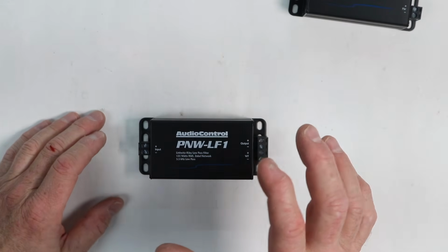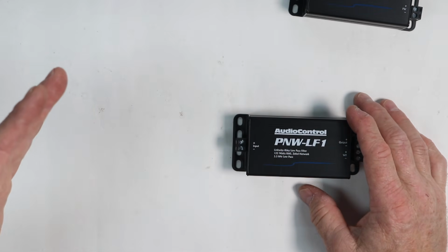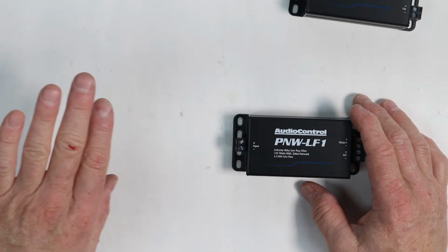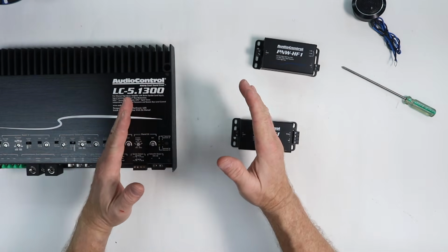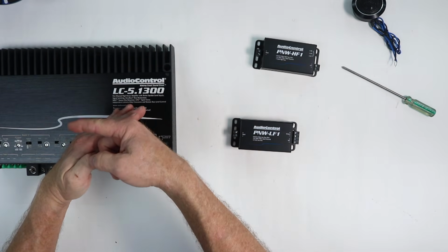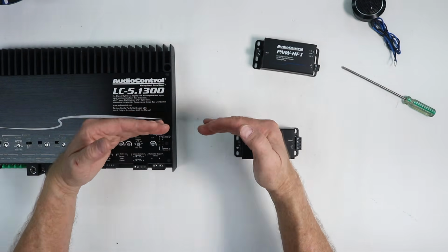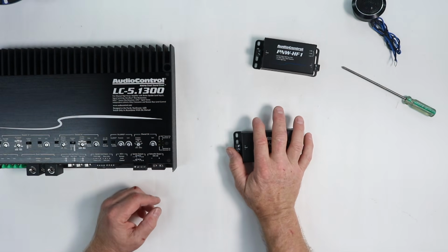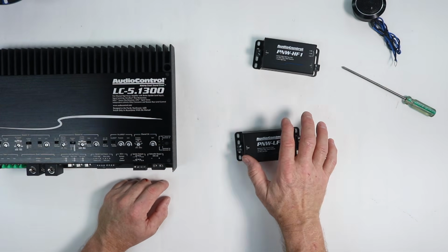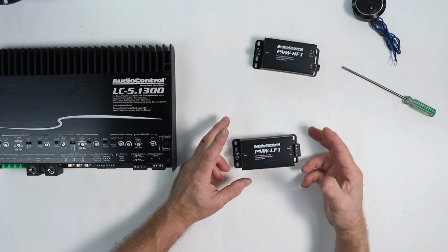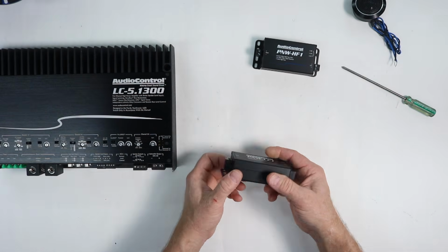The other thing too is that a mid-range, well, it can't play down to subwoofer, so it would need a high pass filter to limit how low it would play. And that was typically done using an amplifier's high pass crossover. And so now what you have is a high pass crossover limiting how low that speaker can play, and a low pass crossover limiting how high that speaker could play. This is what's called a bandpass filter. The top will be passive, the bottom will be active. So this is all done after the amplifier power is going through them. Naturally, a passive crossover has a certain amount of power it can handle just by design, and then that's it. Once you've reached it, it just turns into heat, and these things can get really hot.